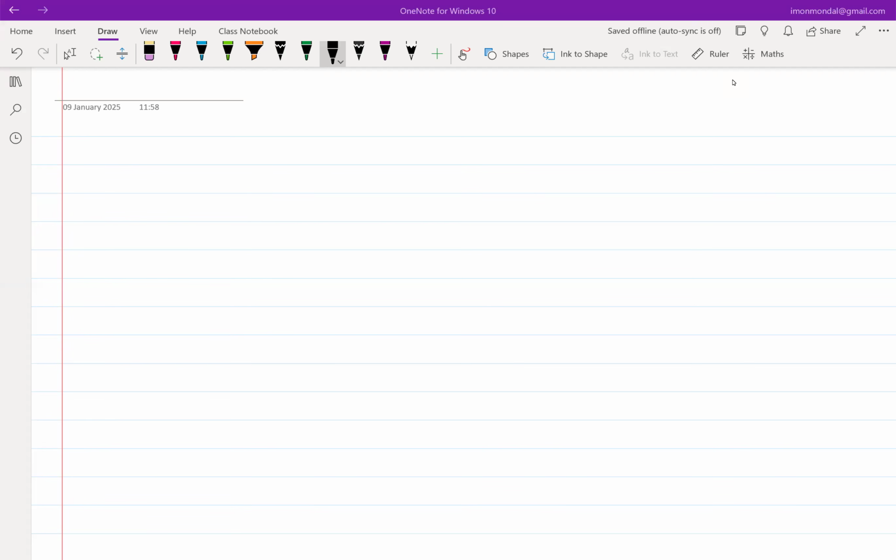Okay, so we were discussing a broad overview of an RF chain, and we started off from the acoustic part, that is, we want to transmit our, let's say, voice signal. Then we said that we are going to convert it into currents and voltages, and then we also said that just transmitting currents and voltages of the audio signal through a wireless channel is not feasible, because the size of the antenna that is required will be of the order of kilometers, maybe tens of kilometers. So that is not a very practical solution.